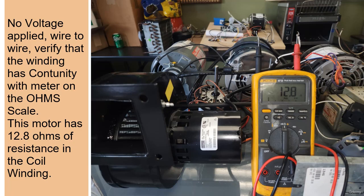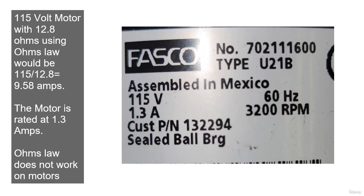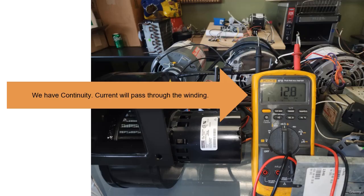The first thing is doing a winding test using your ohm scale. You cannot use Ohm's law. If you have a motor rated for 120 and we use the coil resistance, we will see an amperage much higher than rated. The opposing magnetic field is the resistance. You're just looking for continuity through the windings. You can get specific winding data from the manufacturer if you want to know the exact resistance you should read.